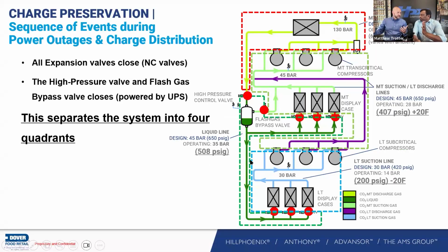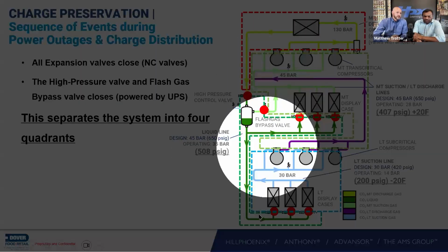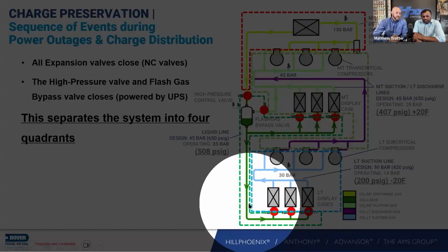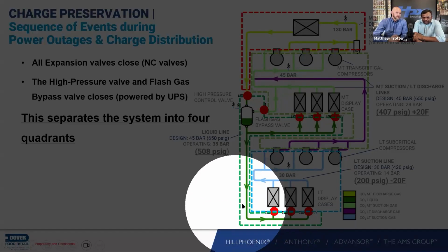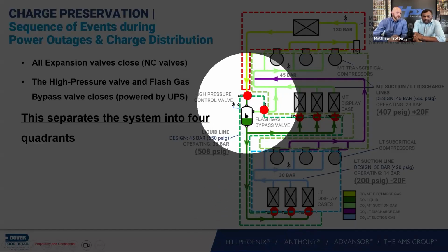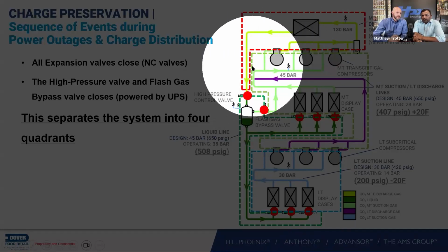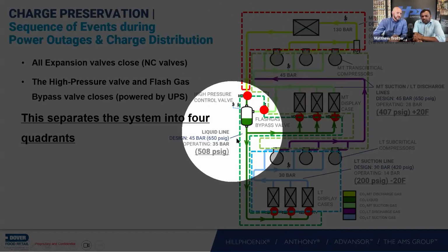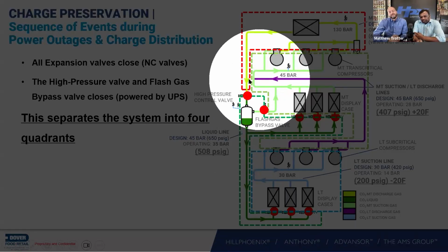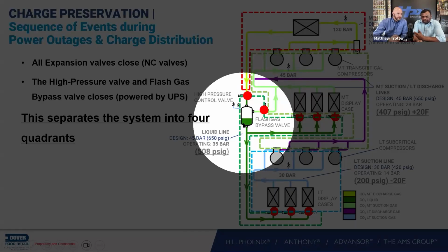So you'll have more surface area, and also more of a system to separate the liquid and the gas. What will happen is, when the heat transfer happens and the pressure goes up, you will push the gas from here to the higher side. The pressure will be equalized first, because it's not closed. So now the flash tank pressure will be equal to the gas cooler pressure, and vice versa, the gas cooler pressure will be the flash tank pressure.